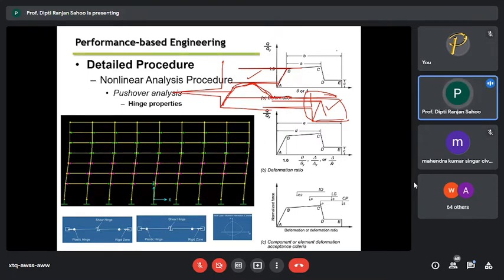Now, this is a unique curve which can define the flexure behavior and the shear behavior. If I say the flexure behavior, I have some kind of ductility between yield and ultimate. In the shear behavior, my B and C will be at the same point. So if I say that A equals 0, the same curve can be implemented.